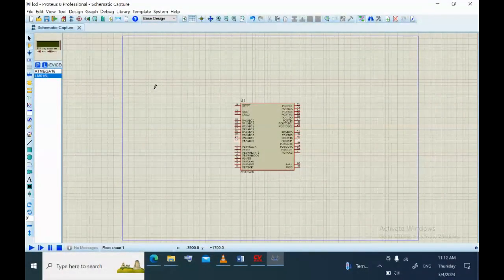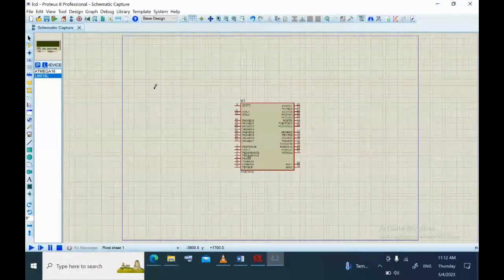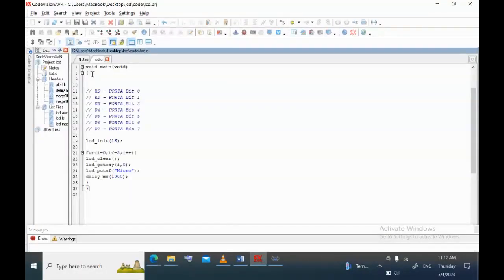As you remember, when we were choosing one port to interface with the LCD in the Code Wizard setting, we chose port A. And also, let me show you in the program, in the comments part that I didn't erase, you see that port A, all of the bits are connected to our LCD, and that's why I said that it's better to not erase these comments.